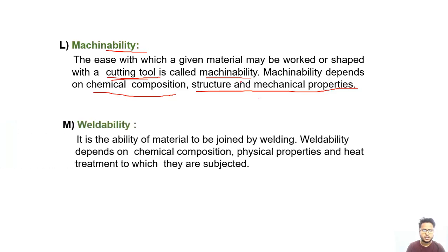The next is weldability. It is the ability of the material to be joined by welding. Weldability depends upon the chemical composition, physical properties, and the heat treatment to which the material is subjected.